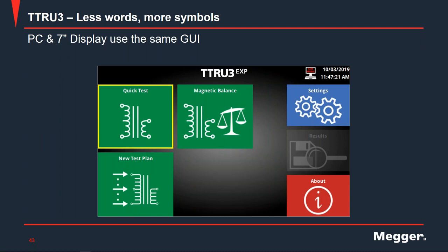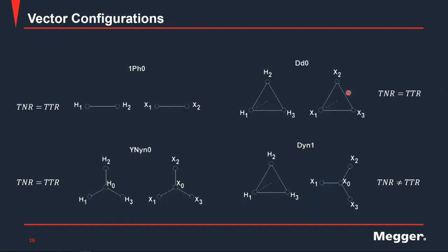But the phase shift that we are calculating during a turns ratio test is between an A phase winding of the primary side and the A phase winding of the secondary side. In theory, the phase angle between the corresponding high and low side phase windings should be 0 degrees. If you get 0.5 degrees or something like that, then that's your phase deviation error.